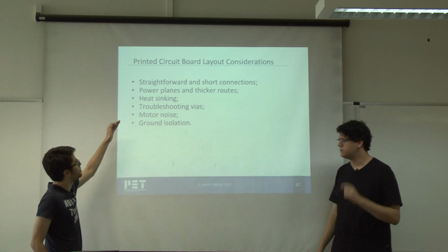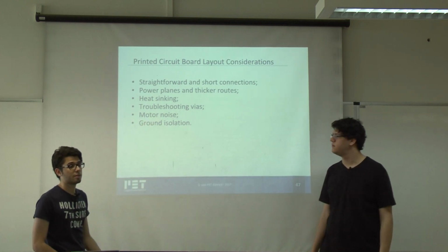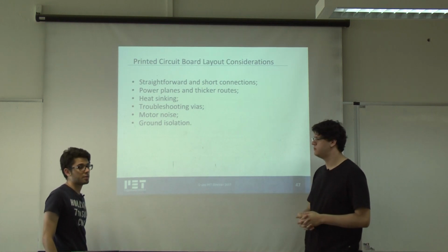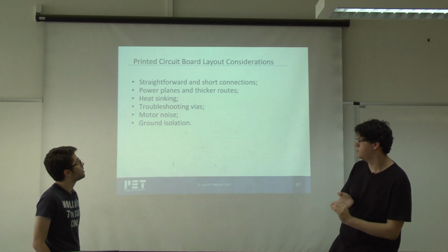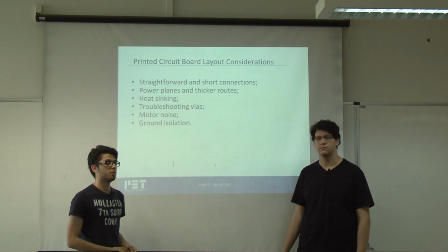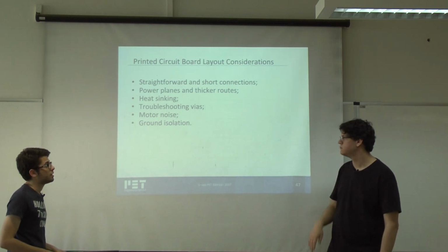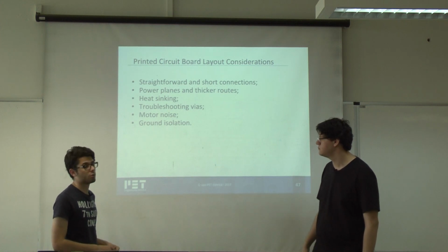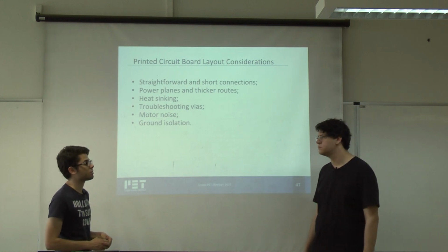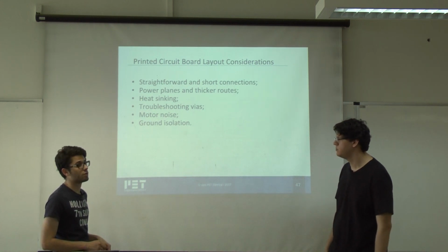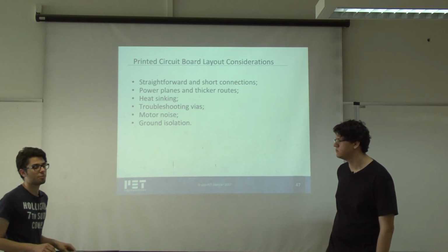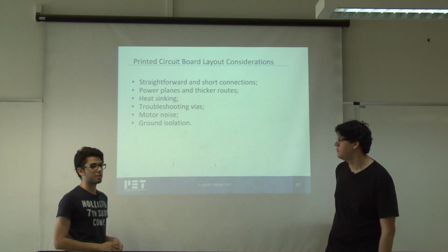It's very important to create power planes to dissipate the current that you will have in the motor because of the inductance of them. So you normally create one for VCC, one for the ground, and one for the microcontroller ground. So the fluctuation of the power this way will affect less than if you don't create anything, because that fluctuation can actually turn off your microcontroller and the system that you have created will just stop working.